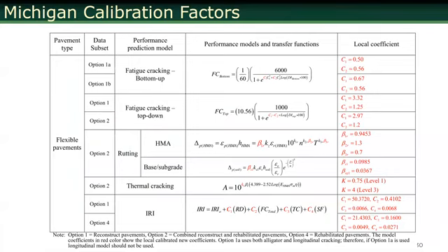These are the calibration coefficients that are used for different models here. One thing that I have to mention is that some people, without running the material tests, material damage models, the flow number tests or beam fatigue tests, try to calibrate these beta values directly to compare with the field distress data. I don't think that's a good idea. It's not accurate. I would also run the material tests and combine them together, so we know exactly what we are calibrating for.